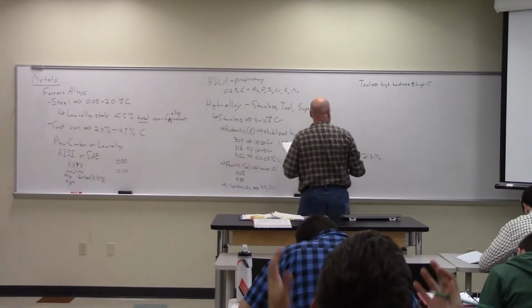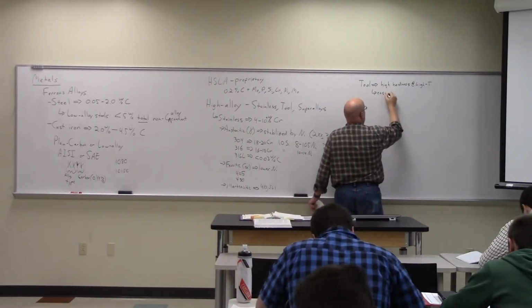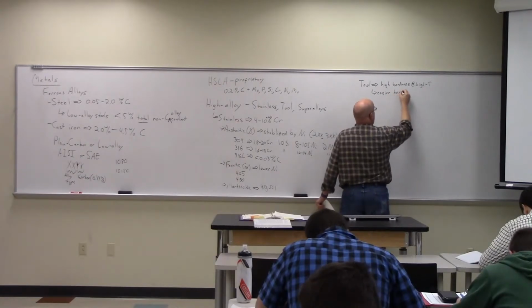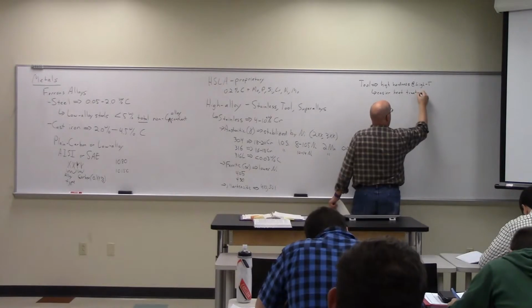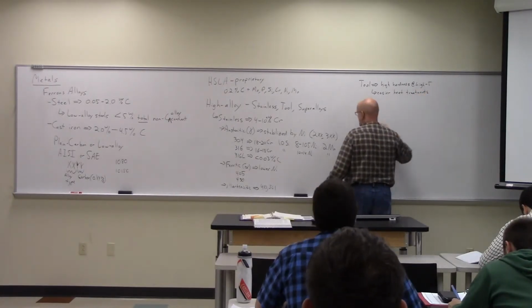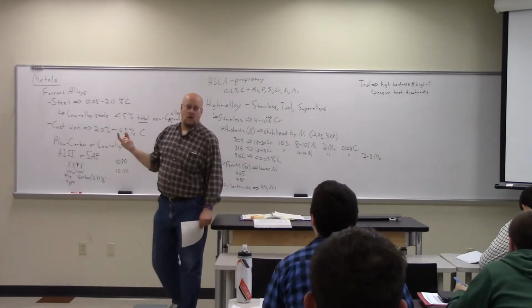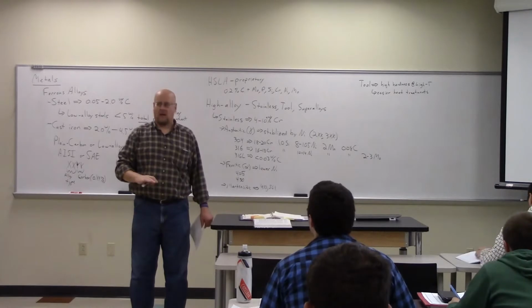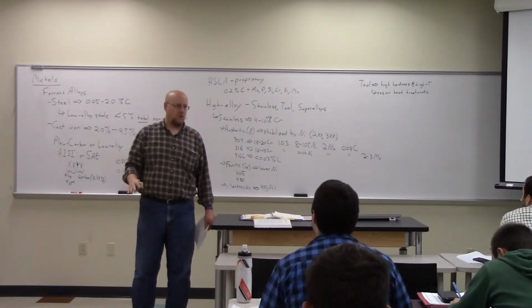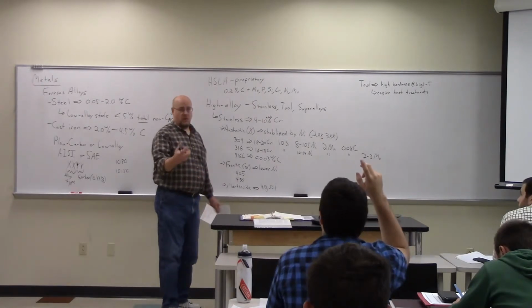And you generally want easier heat treatments. Right, because I can do that with 1080 steel. I can just take plain 1080 steel and get high hardness. But I've got to be able to quench that thing rapidly in order to get down to the bainite or the martensitic transformations. And that's hard to do with a big chunk of something.